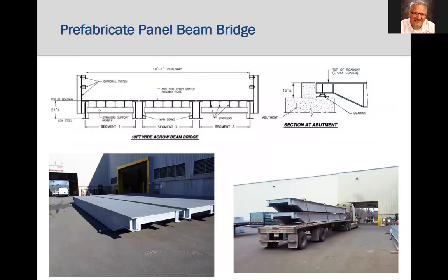The bridge modules are fabricated with pairs of girders, here with a steel orthotropic deck that had a factory-applied epoxy aggregate non-skid surface. All of the steel was galvanized for long-term protection. The modules were shipped to the site and set on the supports, and the orthotropic decks were simply bolted together for quick installation and no concrete curing time. The guardrails were then bolted to the exterior girder.